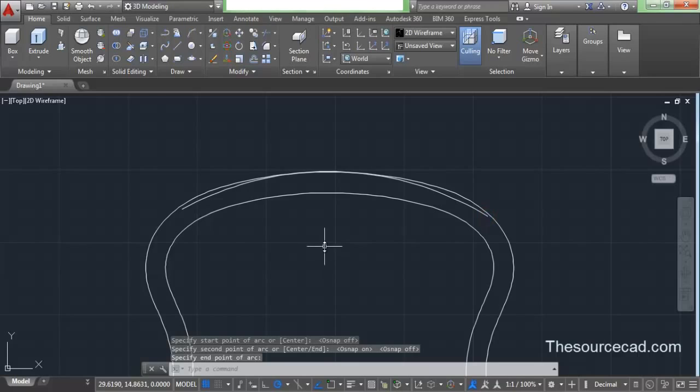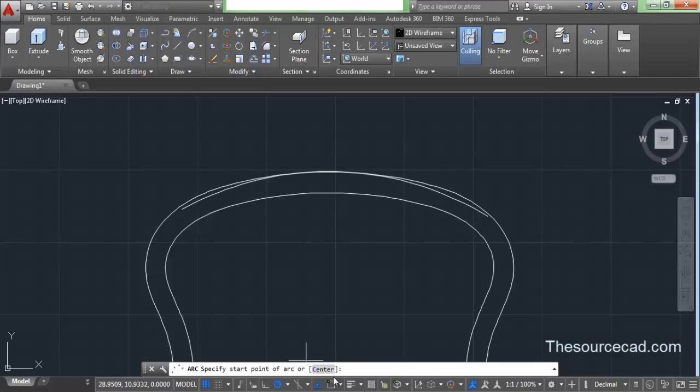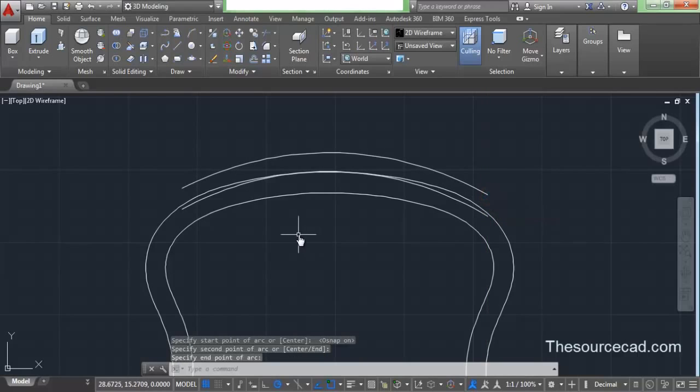It's completely inside this spline, as you can see. And now go to arc again, and now we need to turn it on and track this point and make one more arc. So start from this point and make one more arc which is similar to this. Okay, so here we have another arc. Now we'll join both these endpoints using a line. So go to line and select this point, and we don't need to join it from that point, so make a random point.